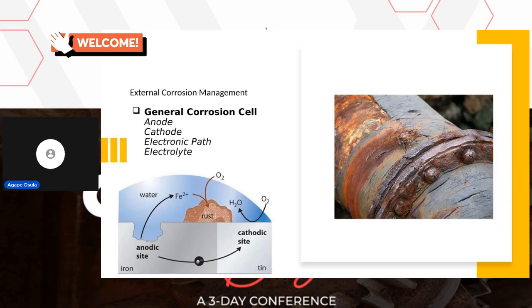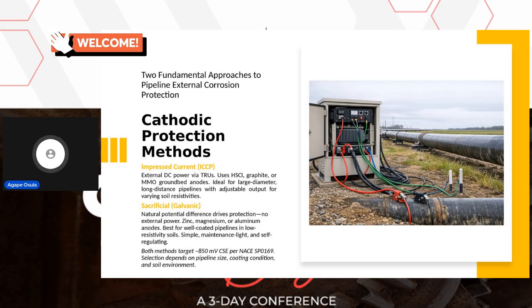Yes, okay, that's good. So generally, for pipeline systems, we have two general types of protection: the impressed current and the sacrificial anode system, or galvanic system. Principally, the concept of the galvanic system is to create the same corrosion cell which already generally exists, but make sure that the one which is corroding is the one you don't want to corrode. So we use things like active magnesium, aluminum, and zinc and the likes as anodes.